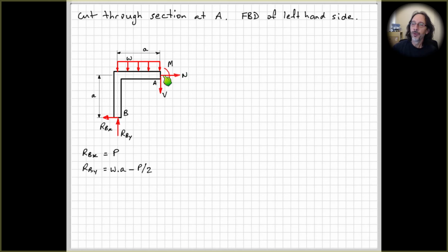And for the normal force, this is the easiest one to understand. Again, we draw it acting out of the section to indicate that it's in tension. If we get a negative value, that'll tell us it's in compression. Shear force acting downwards is positive on this face, and moment anti-clockwise is positive. These are equal and opposite to what we had previously, and I'll show a picture of that again as we get to the end just to compare.